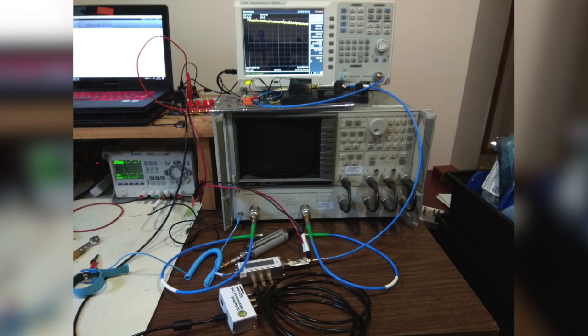You need to consider your setup before you start the test, how much gain you have in your setup, and what you're actually trying to measure. So if you have a 40 dB amplifier, you should know that ahead of time so that you don't add too much preamplification to the spectrum analyzer and overdrive it. It'll become nonlinear, and once it's nonlinear, you can't measure noise parameters accurately or repeatably.